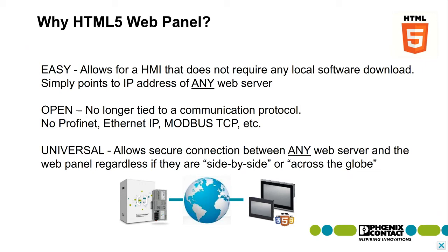But what that actually means is you're not tied to any specific communication protocol. So no Profinet, no Modbus TCP or RTU. Simply plug in an Ethernet cable, connect it via an access point or directly to the PLC, and boom, you're displaying whatever that PLC has to offer. And this is a very great product offering that can just go hand in hand with the PLCnext.